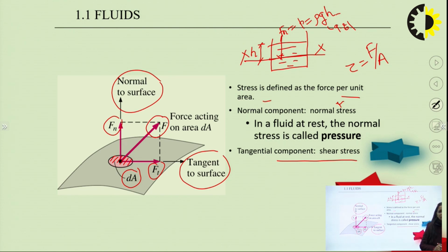See, viscosity is simple. When we are studying any fluid, let us suppose we are taking two fluid layers. In between there is some viscosity. For example, let us suppose the first layer has a velocity of u plus del u, and the lower one has a velocity of u. Let us suppose these layers are separated by a distance del y.